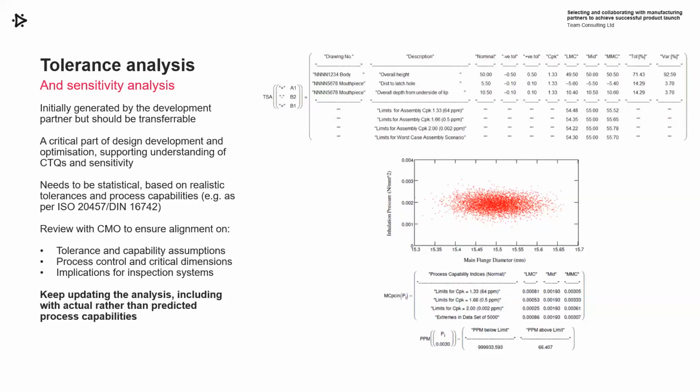Often these tolerance analyses start early on as part of looking at key stacks and sensitivities to them, and then they build into a full tolerance analysis for the overall device or system. It's a critical part of design development. Optimizing it supports understanding of what are the critical to quality features, and the sensitivity of design performance to them.